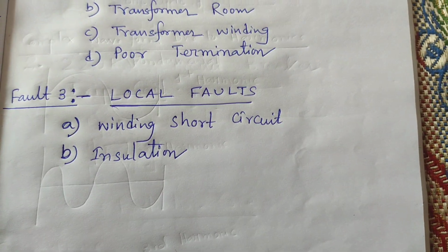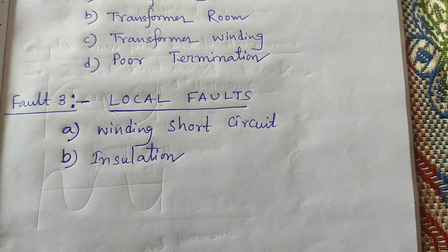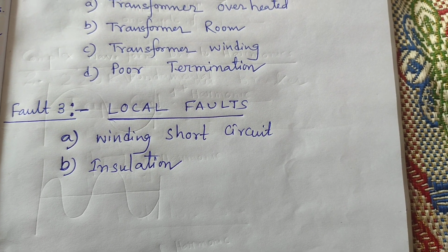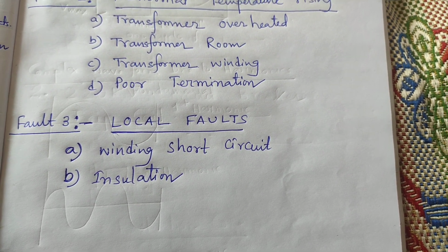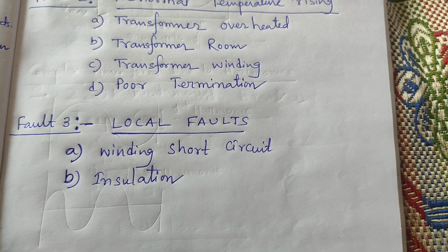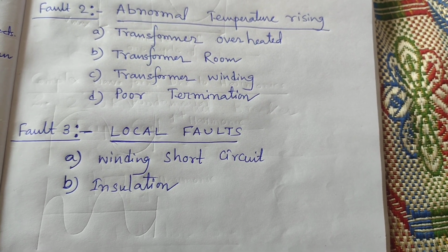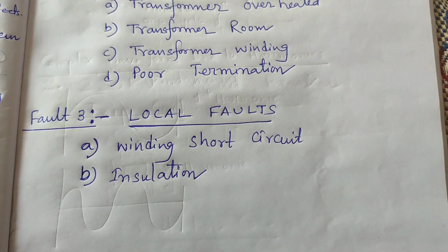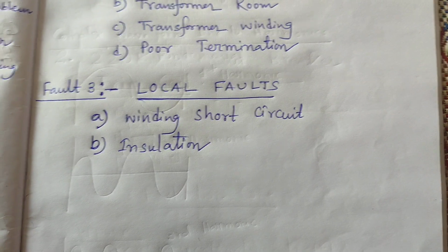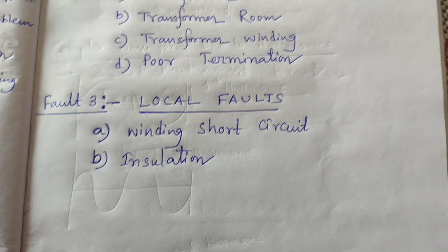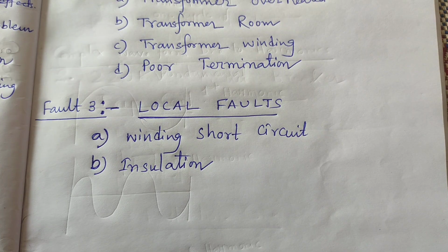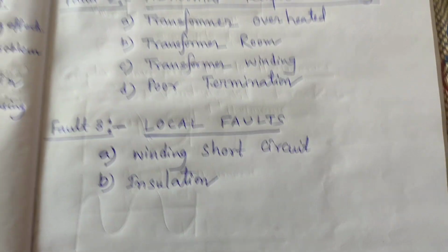So with the help of this switch, we can operate the pump, we can operate the fan, and also the top of the transformer. If you get a shutdown of the transformer, you should go on the transformer main tank body, and check whether the inspection chambers and the NO/NC contacts are properly functioning or not.